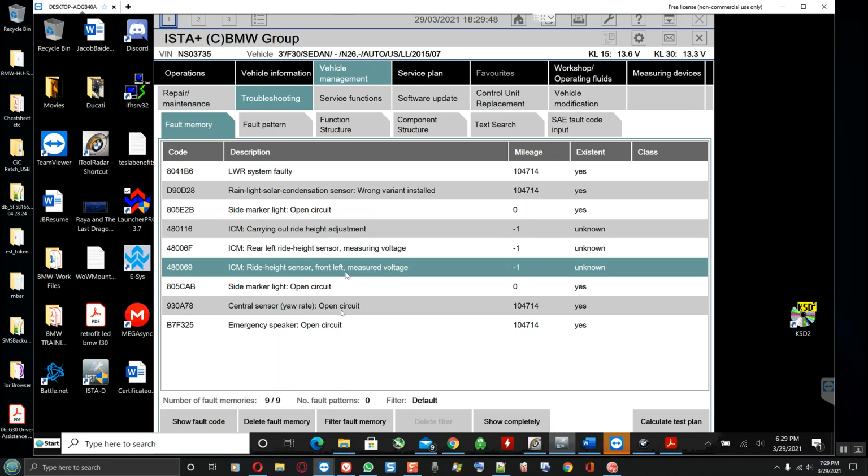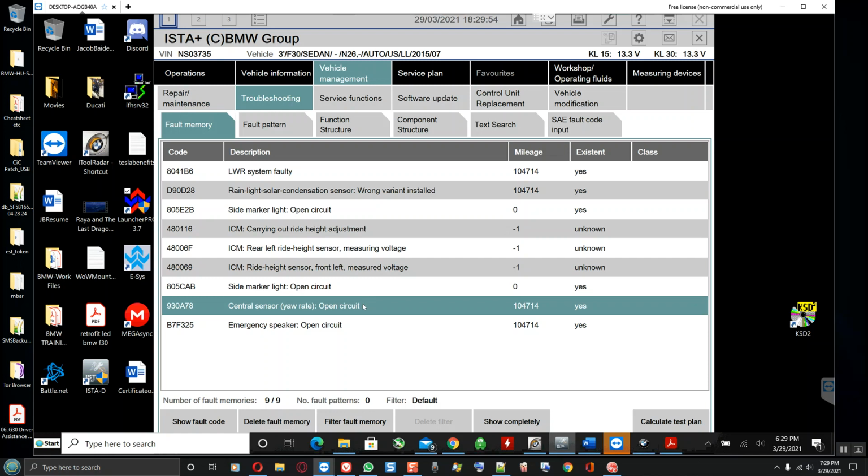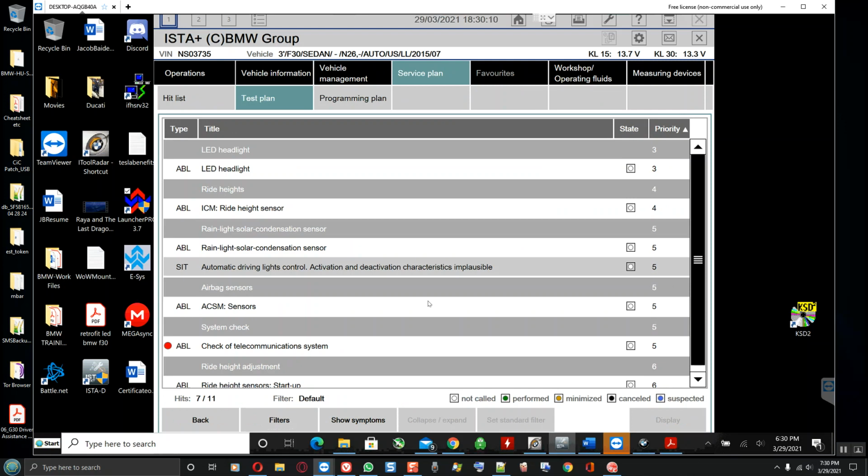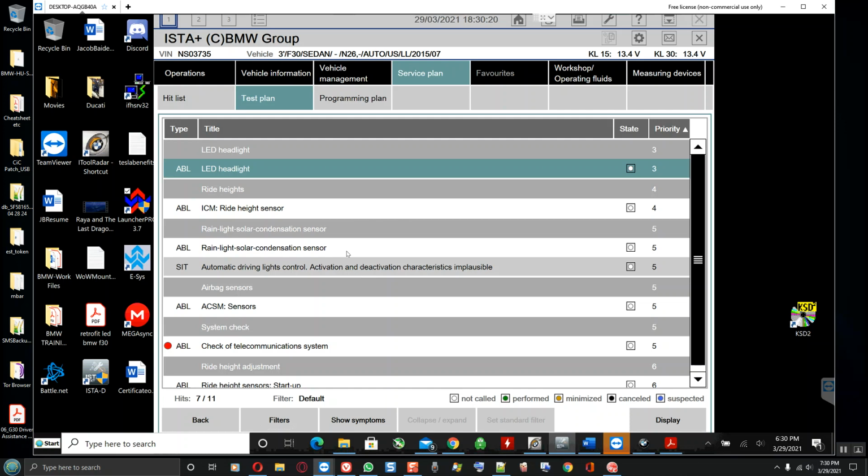Yeah, well, the airbag fault is for the yaw rate sensor, which is reading out fine. Okay, this one that says open circuit? Yeah, that's like the lateral acceleration sensor, so it knows if the car is moving side to side or front to back, or if it's rolled over. And that fault wasn't there prior to when I messed up the coding and then you tried to fix it. The right height sensors, I just haven't run and hooked those up yet, so that's all those are.